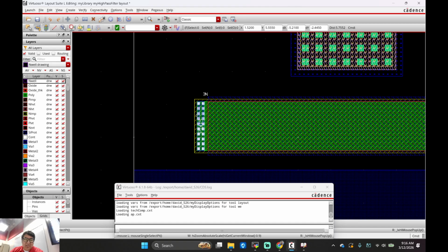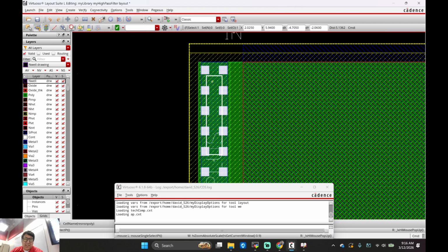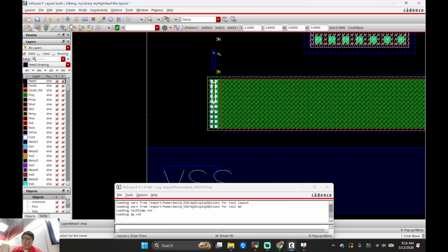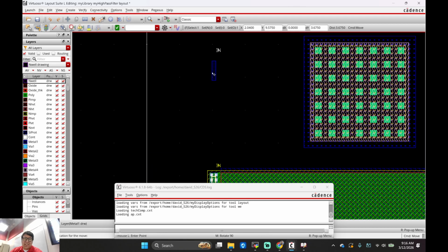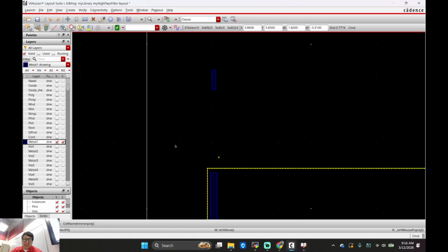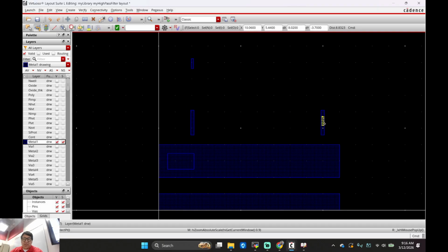So this was a pin that I created. You see this right here? I'm gonna move it. Watch this. Oh, come on. That's my metal 1 pin, right? Do you know why I'm saying to put pins on metal 1? They're pretty easy to find. Don't believe me? Press metal 1, press no view, and then boom. You see all the blue? See that random pin? That's got to be your V out, right?